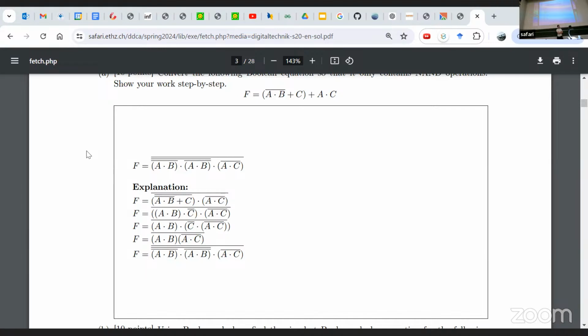It might be implementation dependent, a semantic definition, because there are ways where you can stop this flip-flop from accepting new data. You have an enable flip-flop, so the flip-flop only gets a new value at the rising edge if there is an enable.